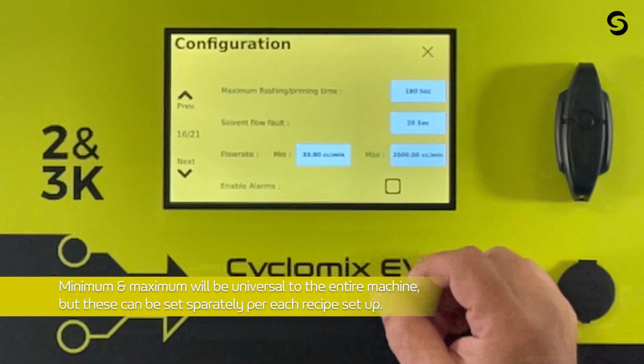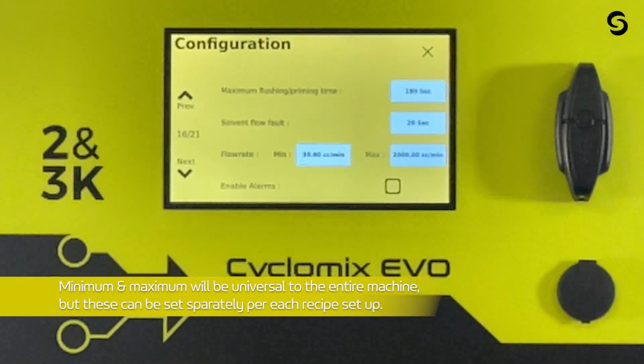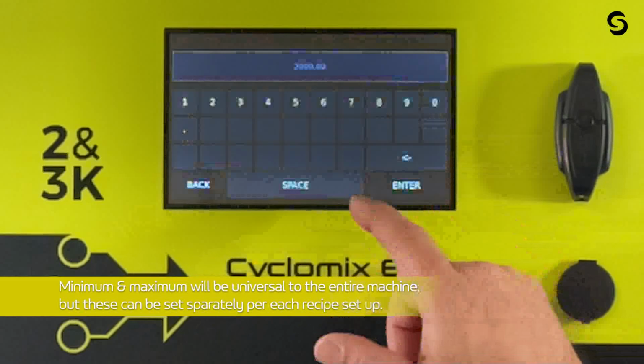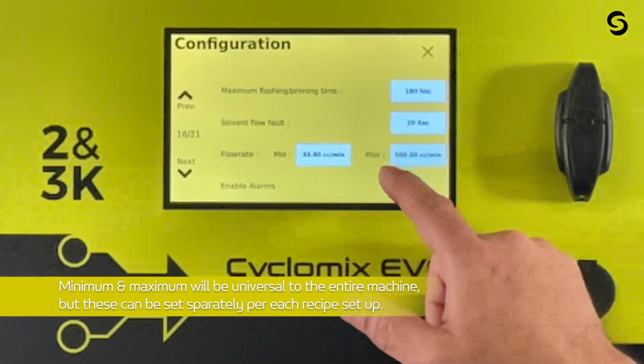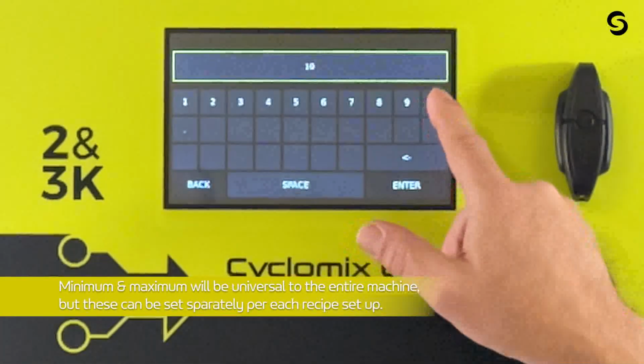Sometimes you may not even want to use this, but we do have situations where, say you have a long hose, they're painting a big piece of machinery or a vehicle, and somebody runs over the hose with a forklift. Well, you can set this down. If you know you're normally spraying at 500 cc's, you could set that for, say, 1,000 cc's.